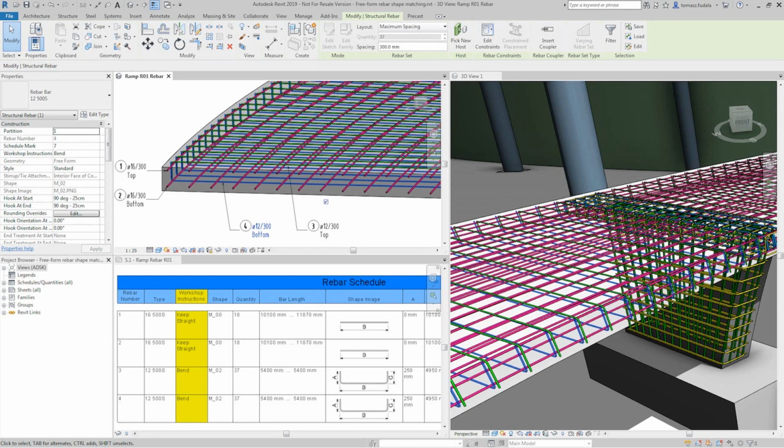We're actually working with intelligent objects with relationships to each other. Again, like I said, it's not just a 2D or 3D application. You've also got the ability to then quantify, or in this particular case, produce a bar bending schedule of all those bars that are located in my model, which takes you to that next level of detail for that fabrication space.